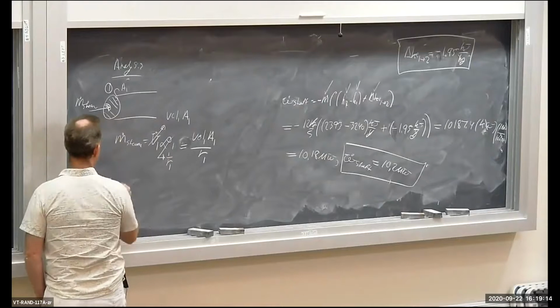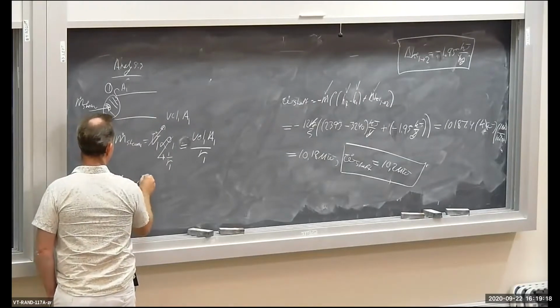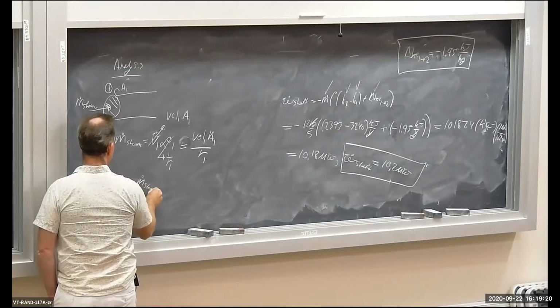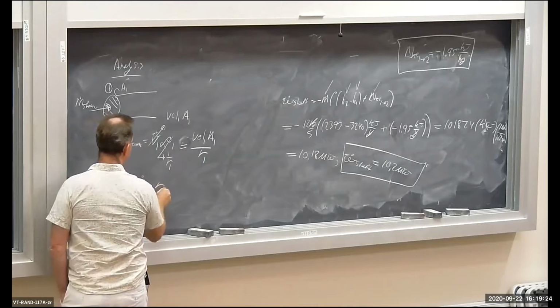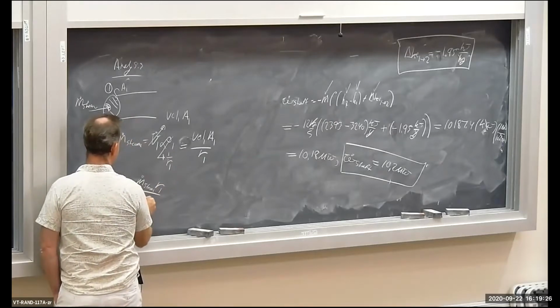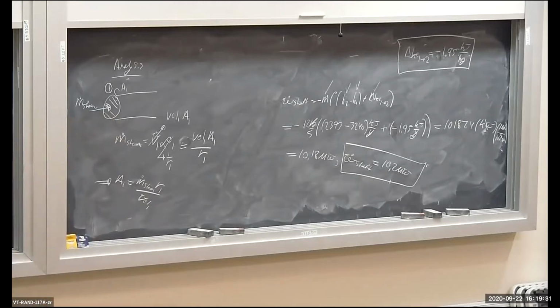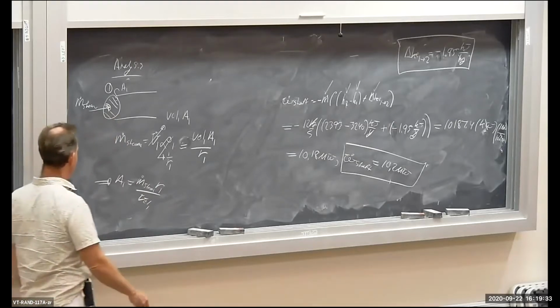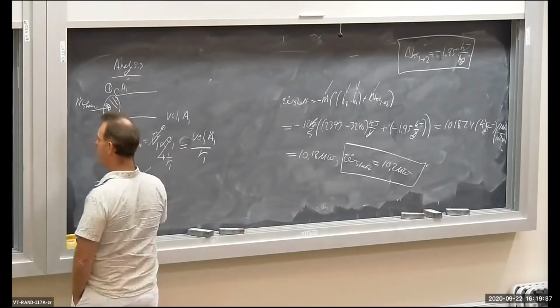So let me solve for the inlet flow area. A1 is equal to m dot steam, or just m dot, times the specific volume at the inlet divided by the flow velocity at the inlet. Okay? Now I have the steam flow rate, which is just my m dot, and I have the inlet velocity, which is 80 meters per second.